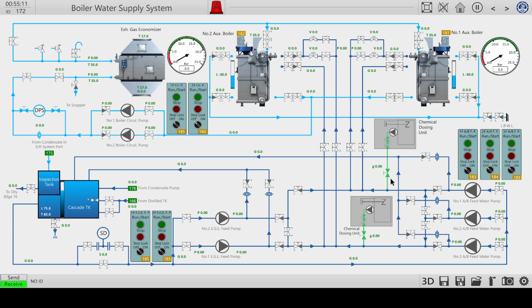Provide the boilers with water from the tanks over here. So let's follow this path down here. The main line, three feed water pumps that have a return path via this line to the tanks, and have a way to feed automatically the first and second boiler.